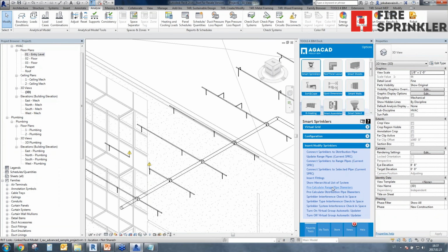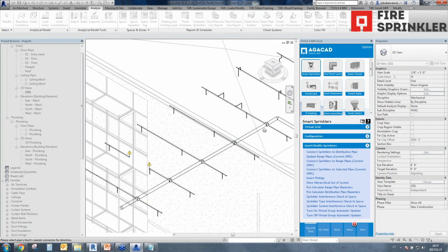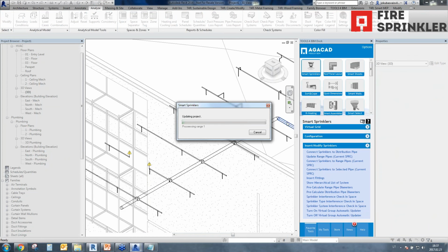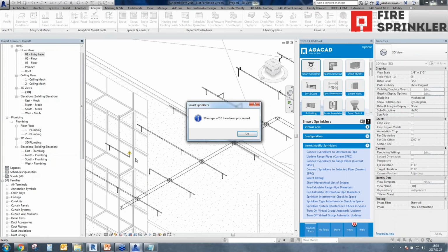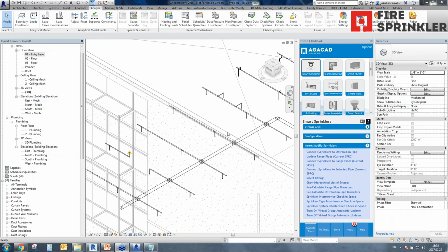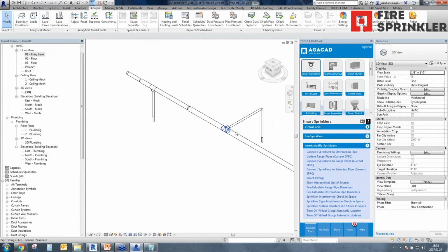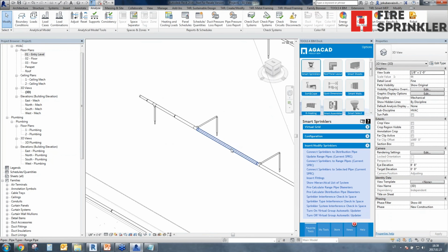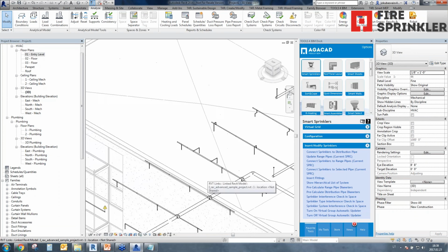Okay, let's work from the other side. I'm taking this feature, and I'm calculating from this point. As you can see, it is recalculating all these pipes. I just accidentally deleted one pipe here, but still, as you can see, my diameter change was here, and right now it just popped to the next section of this.